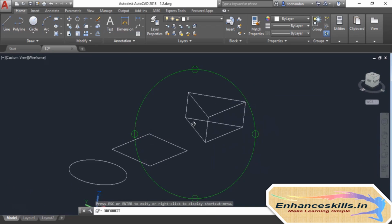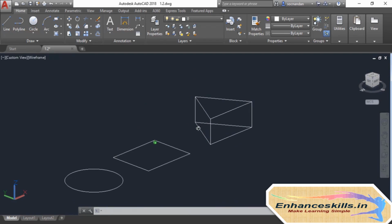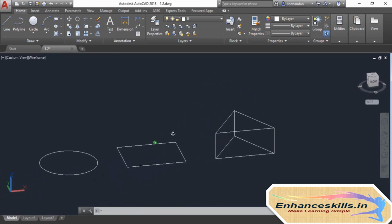So let's press escape key, and now if you want to access the same tool using the mouse, you can do that as well. Simply press and hold shift key, then press the mouse wheel, and now instead of pan, that will convert it into this orbit tool, and now you can orbit the drawing in the free space.